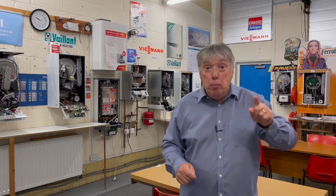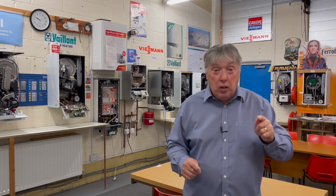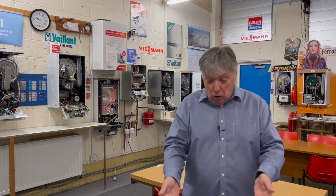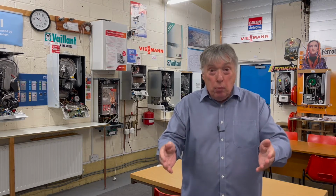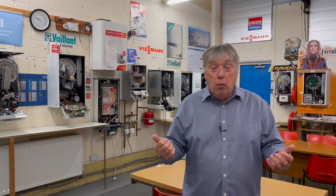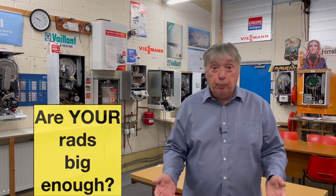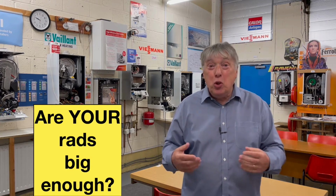Because we know on combi boilers, a lot of them, in fact most of them, can be range rated. When it comes out of the box and it's on the floor, they are all set at 24 kilowatts of radiator load. But as you can see here, I've only got 12. So therefore, my efficiency is 50%. And if I did nothing, my gas bill would be twice the height or twice the amount. And that happens all over the UK because installers don't really bother doing this.